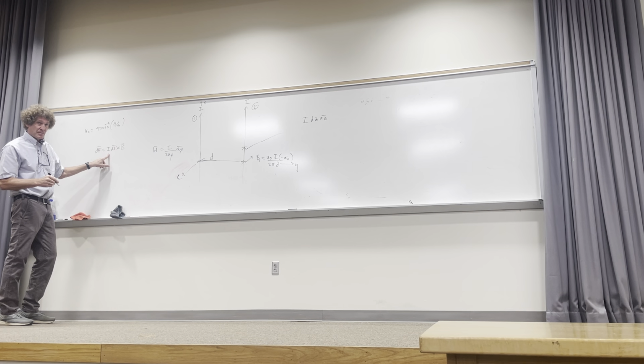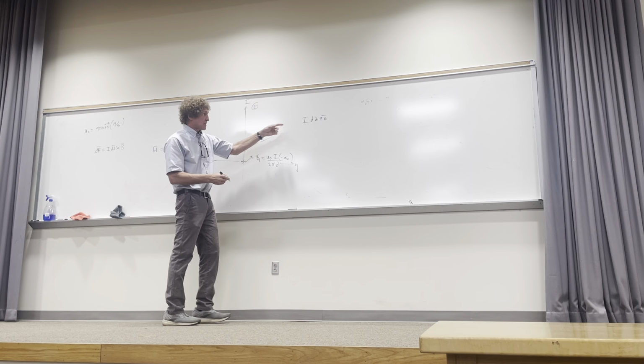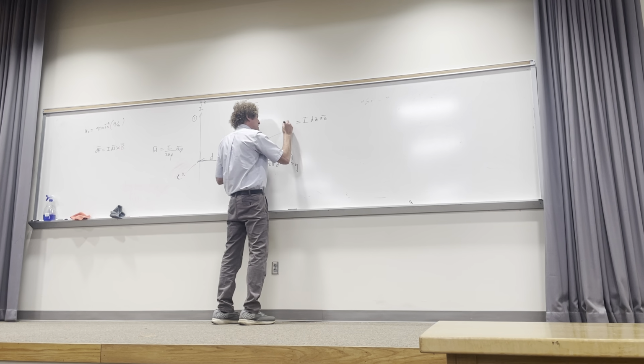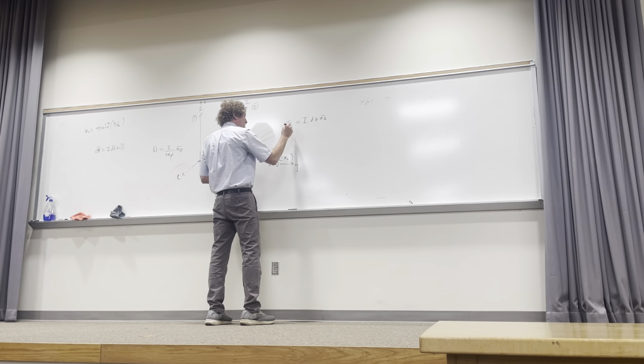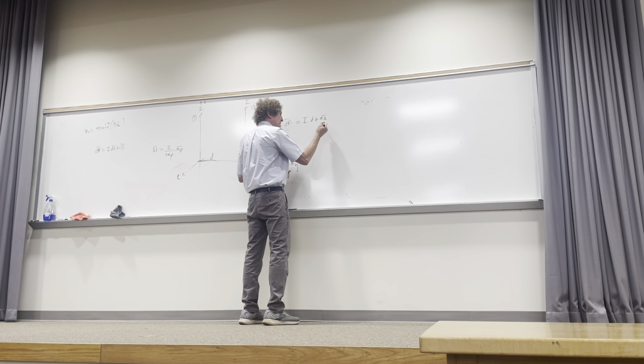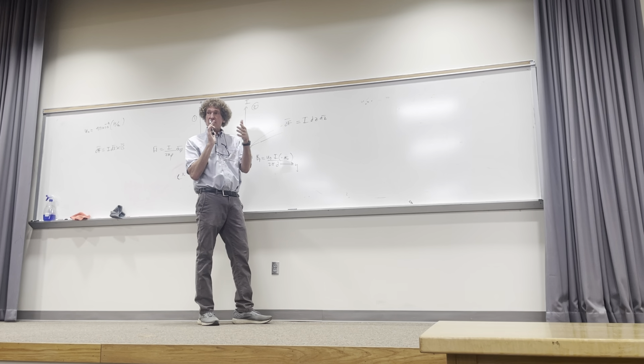Y'all with me, everyone? So when we take a look at this, I'm getting the differential force here on this current element. So it's I dz az, this would be dl. Do y'all follow me? You have to have not only differential length, dz, it has to have a directional sense. The dz az is the direction, it's going straight up.